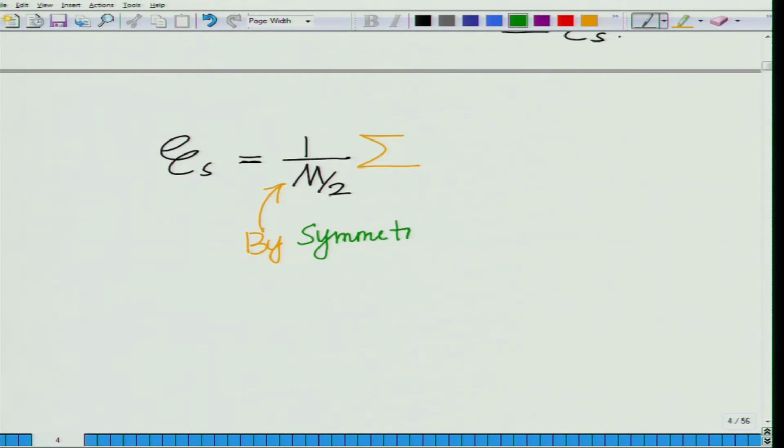Energy of the symbols greater than 0 is equal to energy of the symbols less than 0. Okay, so this is equal to the sum from i equal to 0 to M/2 minus 1. As we have seen, this is (plus or minus (2i plus 1)) whole squared times a squared.